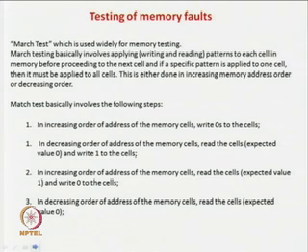In the next lecture, we are going to see, because this is very simple, the idea is that you have to access a memory location, write 0, read 0, and so forth. So here you did not propagate the fault value to the output, you did not sensitize. All those things are not required. It is very simple, because the memory should be able to hold a 0 and a 1, and you should be able to retrieve it when required by a proper addressing mechanism.